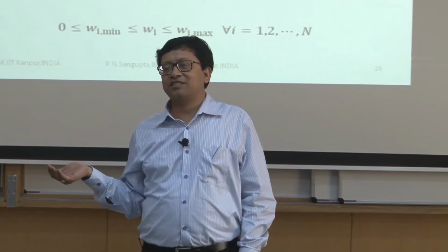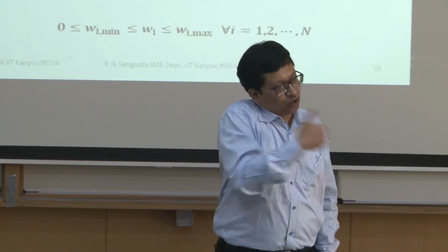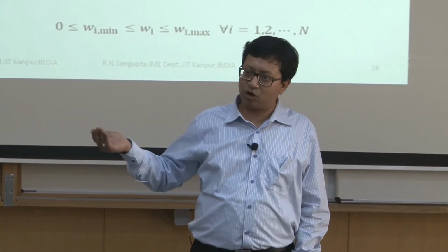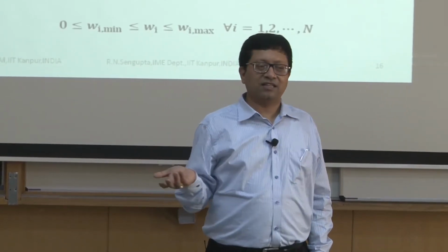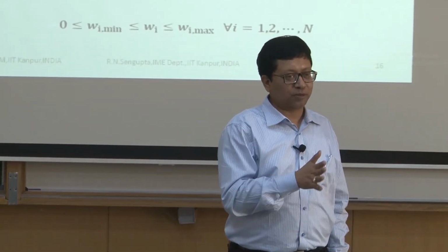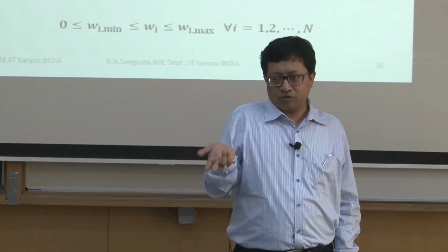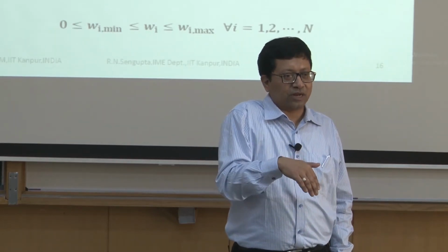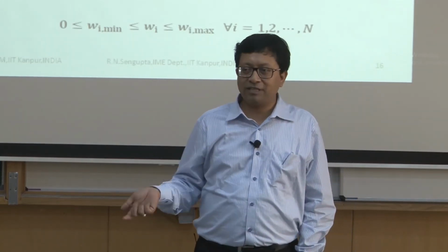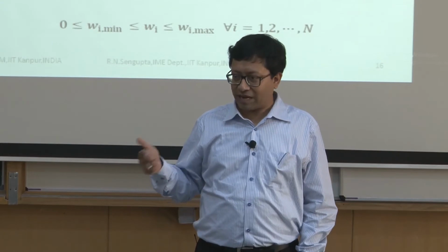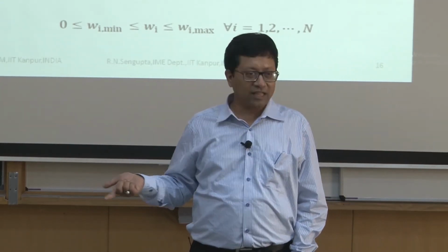So, consider the first case, when it is 7 months. What will happen? The machine will continue working till the 6th month and beyond. So, you will get extra production, which is nice. In the second case, what will you do? You will stop the machine at the 5th month, repair it, and then start again, which means loss of hours, man hours, and production loss. But think from the other side: the probability, the propensity of the machine failing in the first case, which is 7 months, is much higher than in the second case.